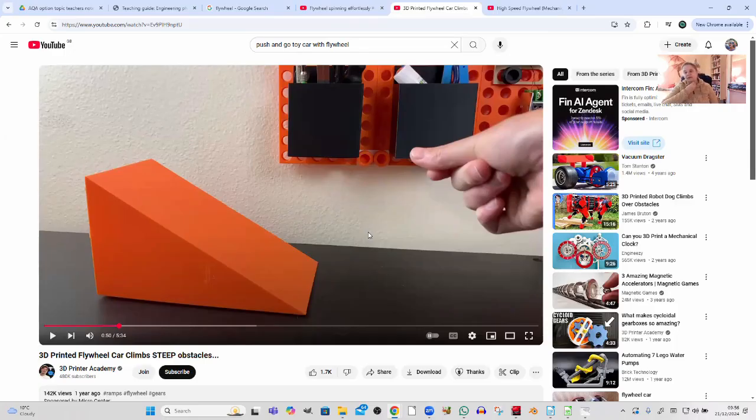And there's an advantage to having a big flywheel that's spinning in a boat, and that is that flywheels also have this gyroscopic effect. They don't want to rotate the axis of rotation. If you force the axis of rotation to move, then it kind of pushes back on you and makes you spin the other way. What that means is that a big flywheel spinning in a ship will stabilize the motion of the ship.